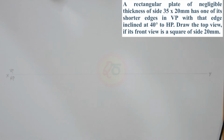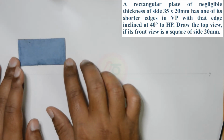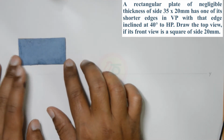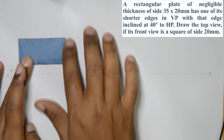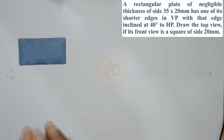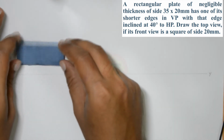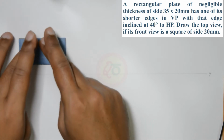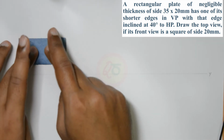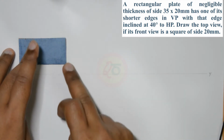So the question states that the plate is resting in VP. So what we need to do is draw the rectangle in the VP space, in such a way that one of the shorter edges lies on the right side. This is how the first view is, which is the front view, since it is resting on VP. The front view is a rectangle resting on VP, in such a way that the shorter edge is perpendicular to the XY line.